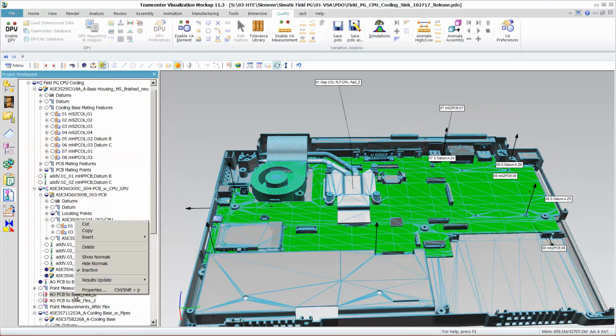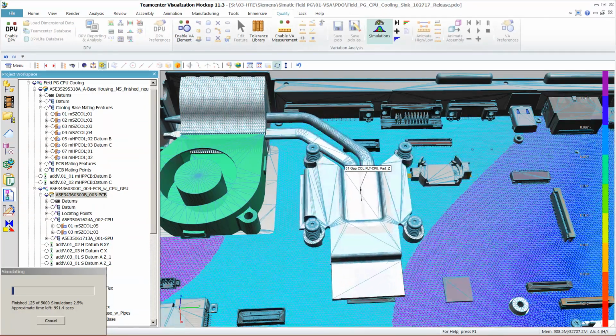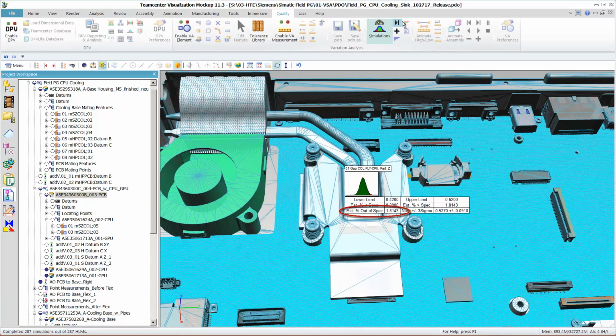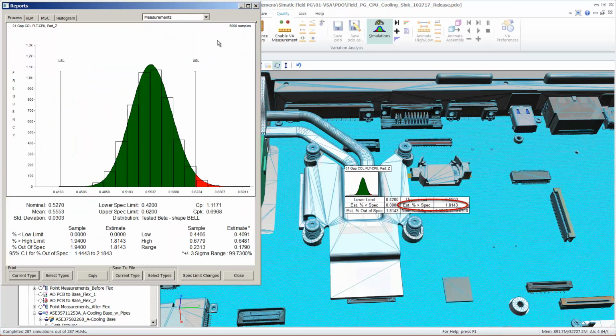Let's activate this Flex operation and run simulation again. Well, as you can see, the out-of-spec percent for the gap drops down to 1.82% from the previous 4.45%. We are now at 98.18% good quality rate, still below the required 99.73% Six Sigma quality rate though. Now it appears most of the out-of-spec products are with 2 big gaps, which could cause excessive CPU heat and fan noise.